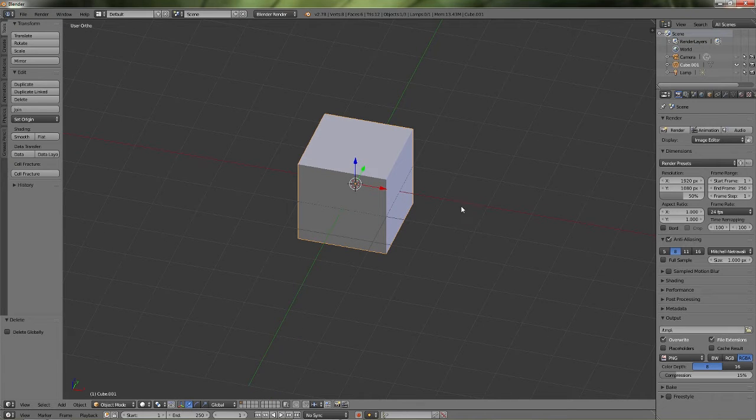Now, one thing that can be very useful if you're adding a lot of different meshes in here is renaming. Just double click and you can type in whatever name, whether it's your desk or your barrel or whatever you're creating. It's a good idea to rename your objects, so that if you have another file and you're importing stuff, you're not like, oh my gosh, which Cube.001 or 2 or 5 do I want? Oh, this is my barrel, this is my desk, this is the fancy desk. It's a good idea to rename and keep your files organized that way.